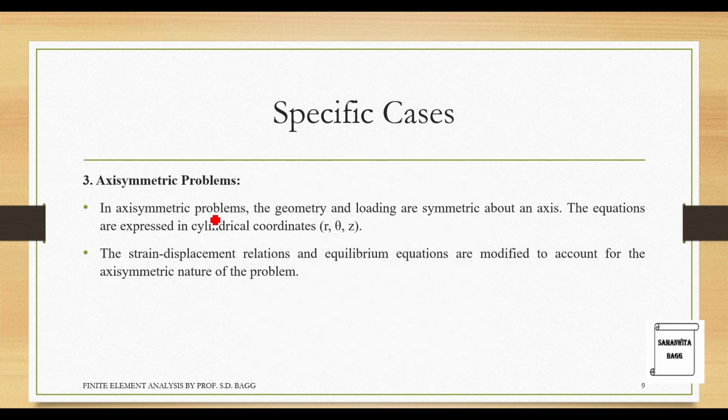Specific case number 3 is axisymmetric problems. In axisymmetric problems, the geometry and loading are symmetric about an axis. The equations are expressed in cylindrical coordinates r, theta, and z form. The strain displacement relations and equilibrium equations are modified to account for the axisymmetric nature of the problem.